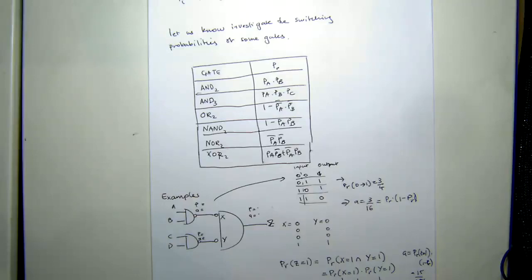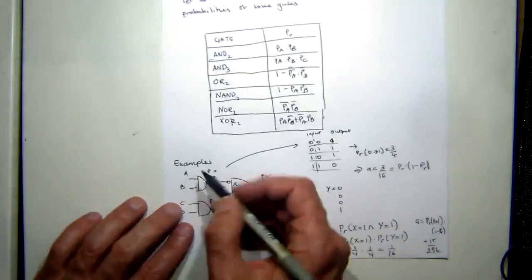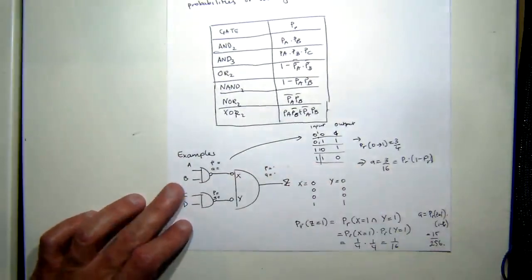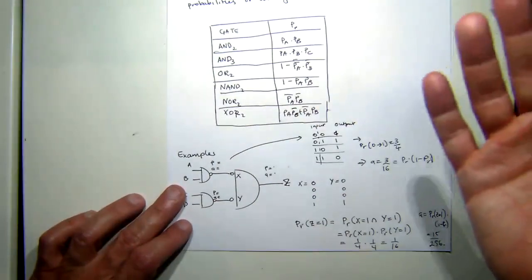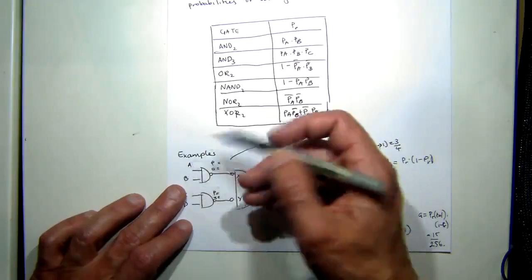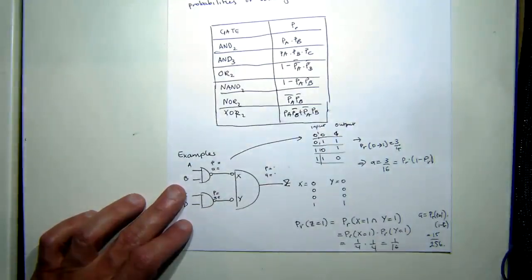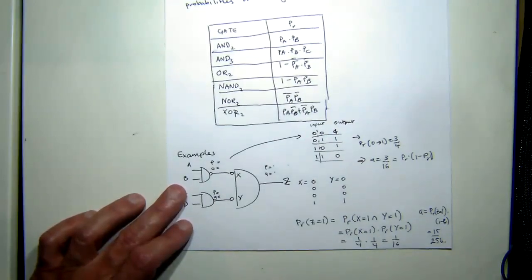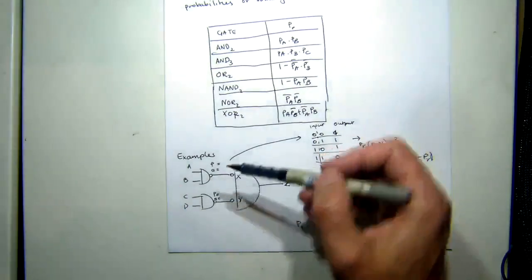Here I've got a NAND gate with 2 inputs, and what I'm saying in this particular case is the probability of an A or a B is 50%. I either assume that, or I'll tell you otherwise. In most cases, assume the probability is 50% because that's what it usually is. If it's not, somebody will have to tell you it's some other probability. Okay, so now let's look at the output for this node.